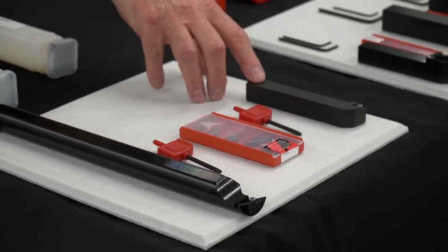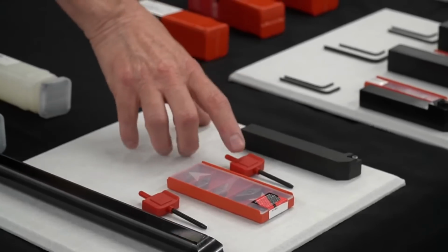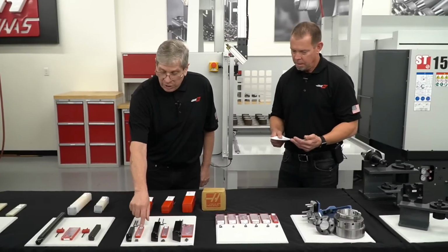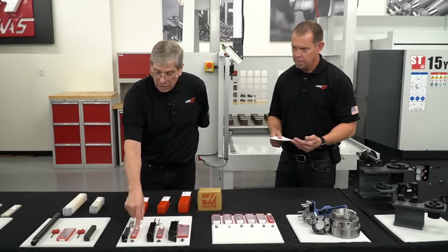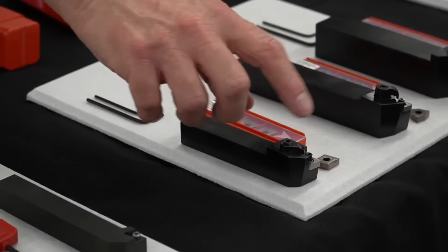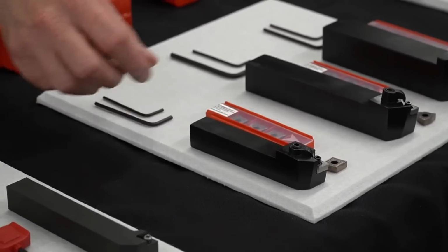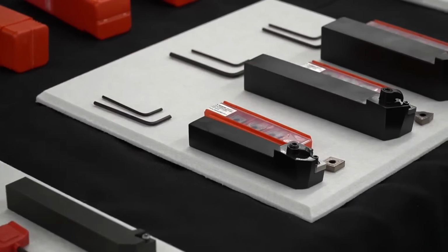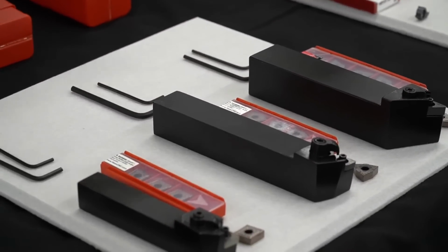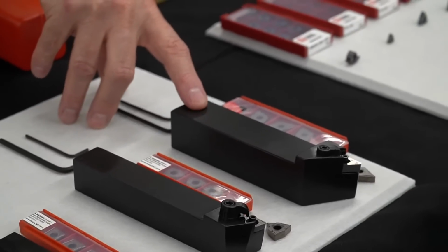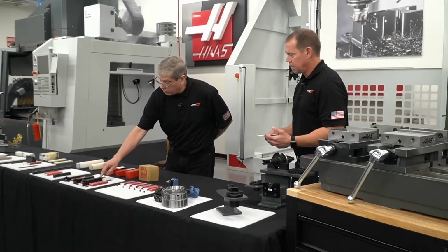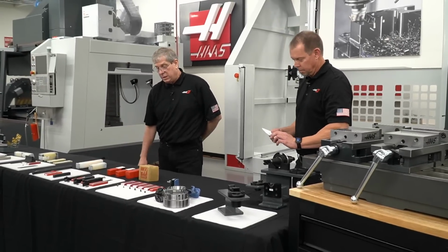I've got a smaller CNMG tool holder. Again, that tool holder comes with the Torx wrench. And then the next size over, CNMG 432, your basic workhorse in turning. Each of these tool holders with the top clamp style come with the 2 hex keys needed to install those inserts. Here's the larger 1-inch tool stick with the Trigon style insert. The next one is the 55-degree diamond tool holder in the 1 1/4 inch size for your larger machines. Again, they all come with the hex keys.